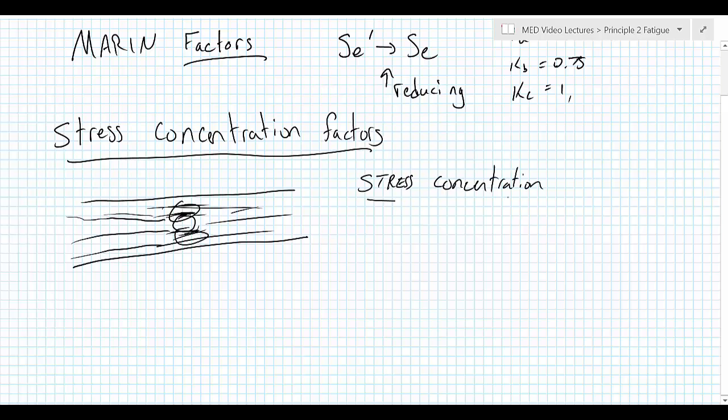Now recall for ductile failure, that was okay. We don't mind that the stress concentrates there because when it does cause those little tiny cracks to form, it ends up relieving some of the stress. And so we don't have as much of an issue with ductile failure. But for brittle failure, it was very important. Well, fatigue failure is that loading happening over and over and over again. And over time, you've got a part with maybe just the tiniest little inconsistency at some geometry change. And as we load this thing many times, that crack starts to grow. And as it grows, that stress concentration grows higher.